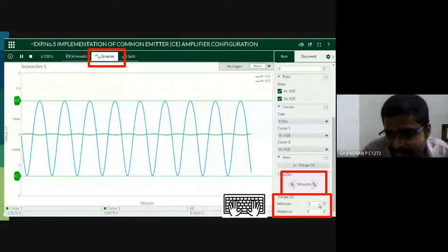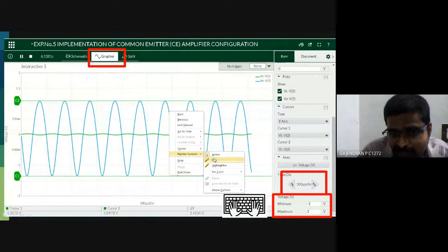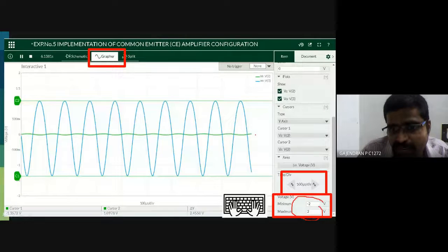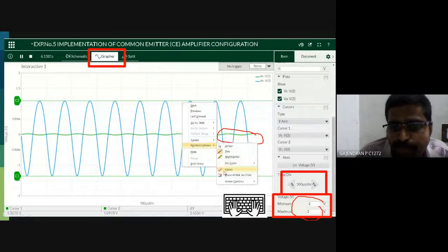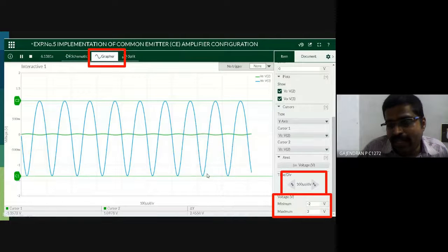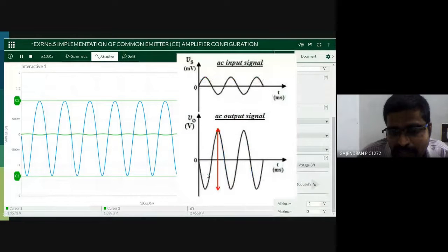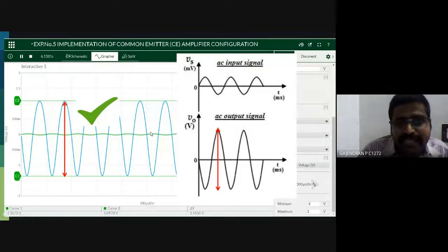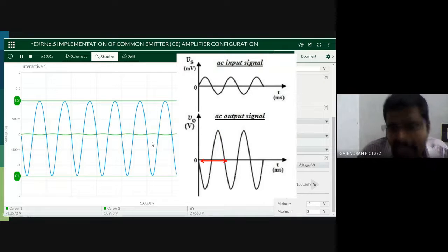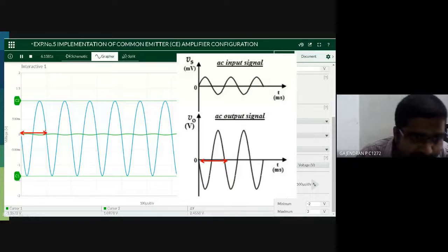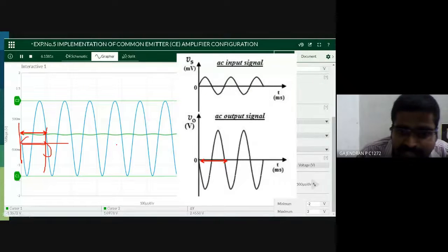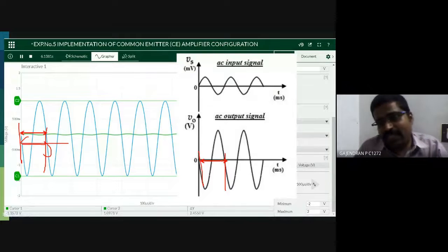Again, change the minimum and maximum value setting for the input value. How much should we set? It should be in the millivolt range. Now I have seen the output magnitude clearly. Now I need to see the input. So change the magnitude into millivolts. Okay? This time you will draw it yourselves. Whether you measure this and draw, or calculate the time yourself using the 10 kilohertz you set and draw, that is up to you.